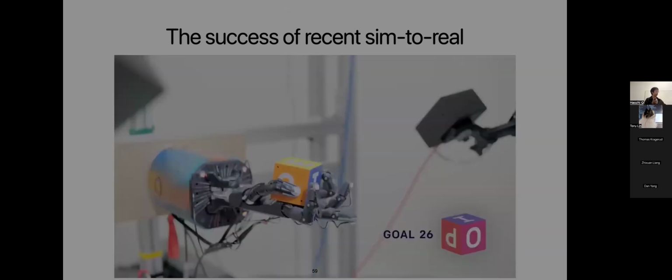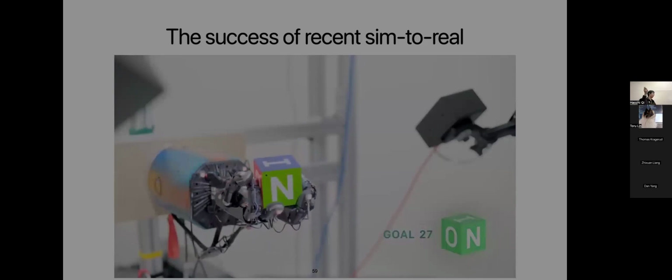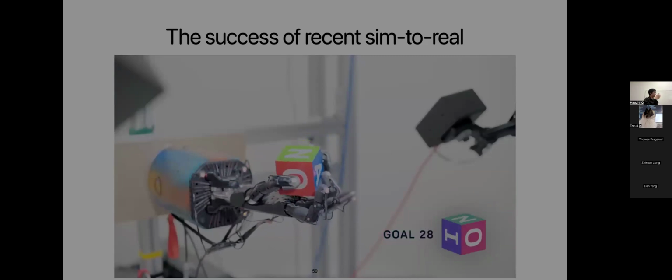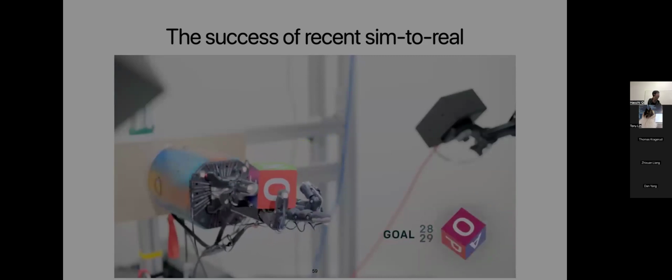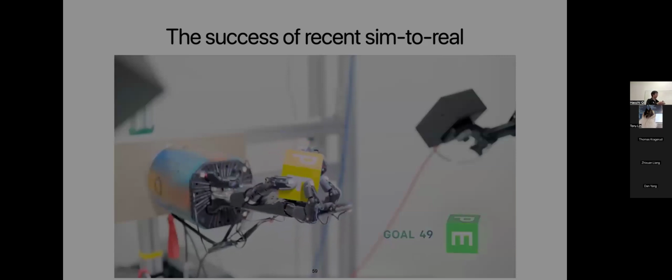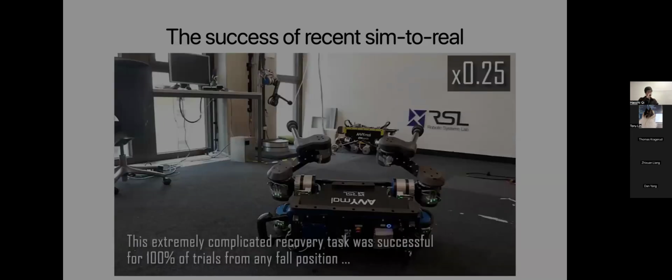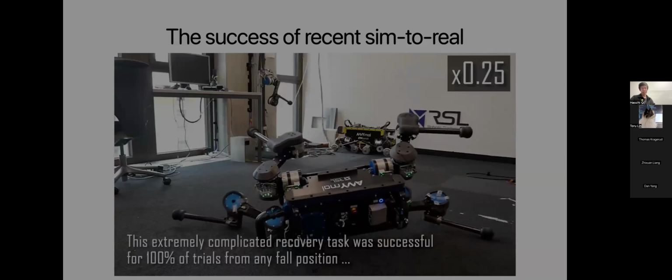So if you are doing traditional control, MPC-based methods, the search space is quite huge. Basically each joint has a binary number. If you only consider binary contact, each joint can either be in contact with the object or not. So you have maybe 26 joints, then you have 2 to the power of 26 possibilities. This is a very hard search problem, and previous control-based methods cannot do that. And this extremely complicated task was successful.